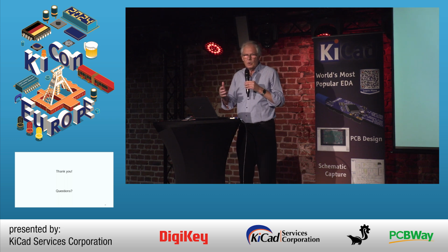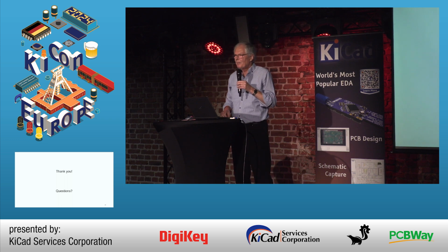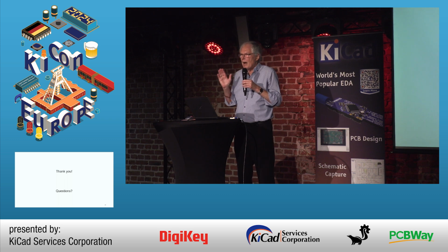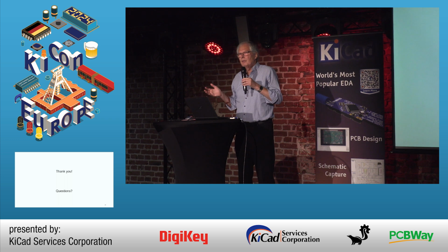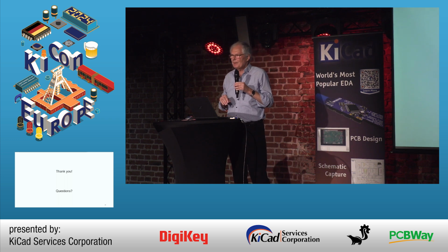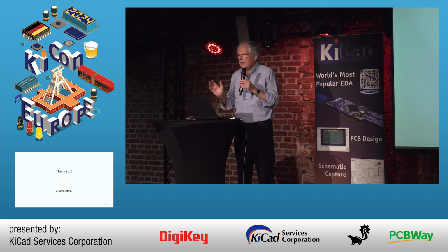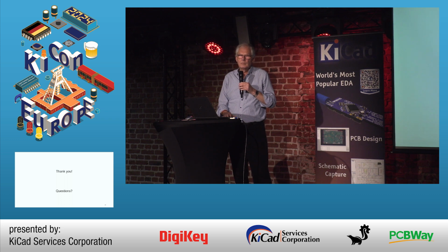You could think about doing this a little bit more integrated. Well, why not make a rectangle? But you cut some wires, and you have to cut these wires somehow, and you have to put SPICE voltages on. And to automate this, I don't know. It could be done, perhaps. But for now, I would recommend small circuits, simulate them directly. Larger circuits, put them into individual blocks, copy them and then simulate.